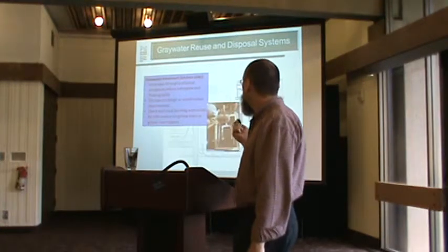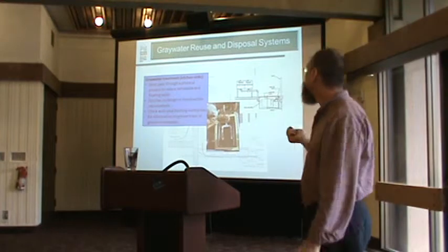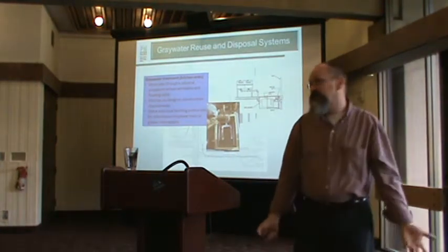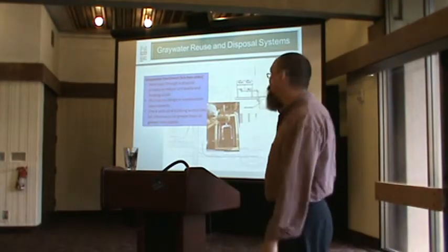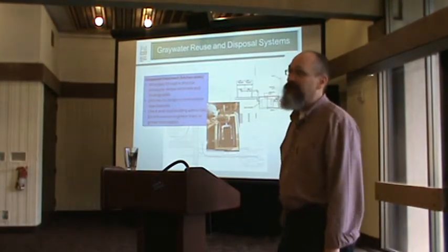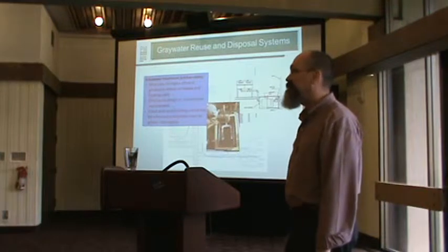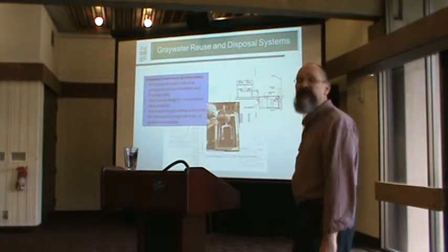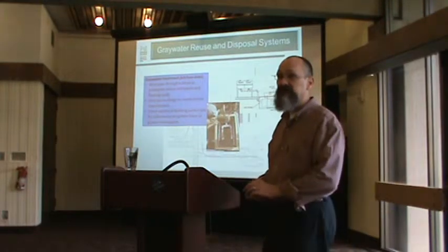So, diversion device. Graywater treatment from the kitchen sink. So this is kind of that question that was coming up. We don't specify what sort of physical treatment and what it's going to look like. So it could be a commercial grease trap sort of setup. They can be expensive and they're not nice to maintain, but a grease trap is an option to put underneath your sink.